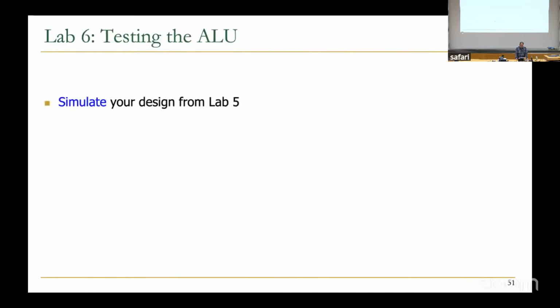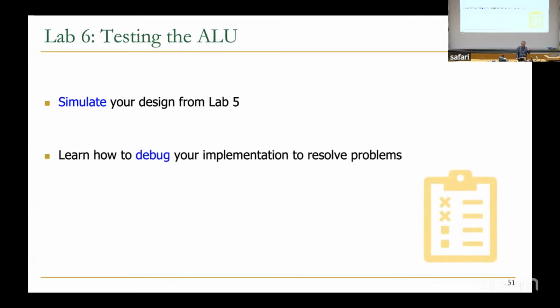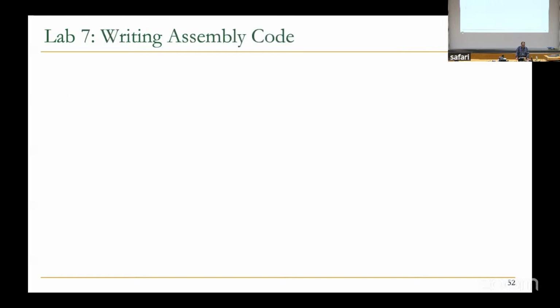Then in lab 6, we're gonna test our ALU. Basically, whenever you design something, you need to verify it. That's the verification part, where you need to design a test bench to simulate your design. In lab 6, the focus is to teach you how to simulate and test the functionality, essentially. So we learn how to debug your implementation and to resolve problems.